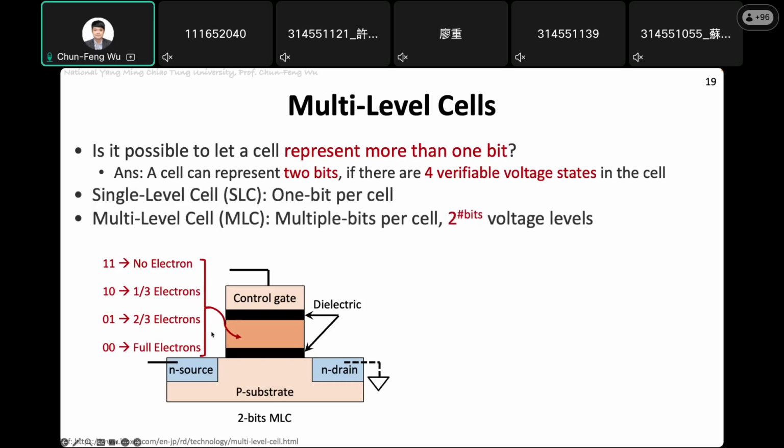So when you go to buy an SSD, if you see something called an SLC SSD, the full name is single-level cell, which means each cell holds only 1 bit. If you see MLC, it usually implies multi-level cell, so multiple bits per cell. The bit number depends on it; if it is MLC, usually it's 2.